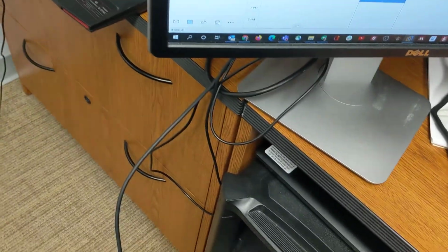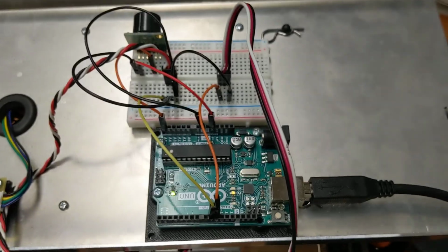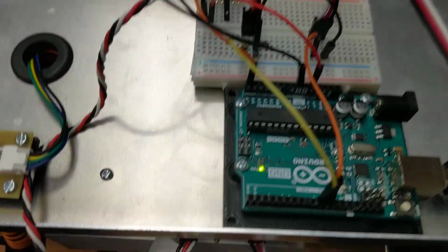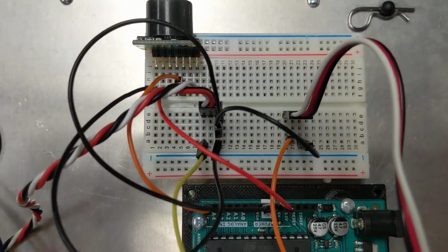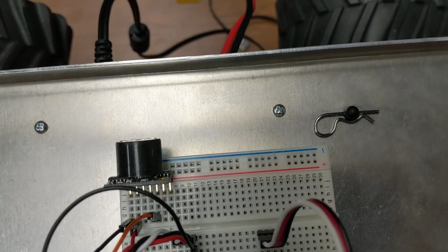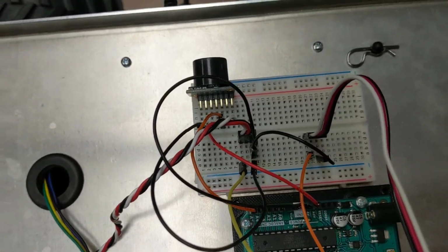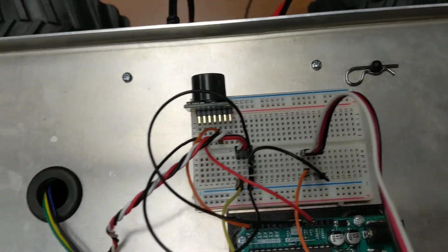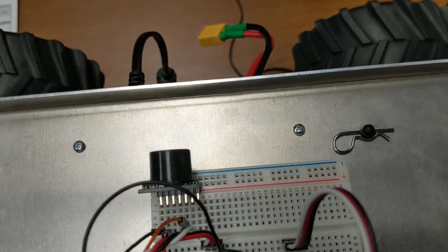So the serial cable goes to the Arduino, right? And this is getting powered from the Arduino. Here are the 2 servo channels, pins 9 and 10. I'm just jumpering those over to this PCB board. And again, all I'm doing is sending signal and ground. I'm not powering the vehicle. So do not power the servo channels because they're getting power from the actual vehicle itself. You could just hook up regular servos for testing.